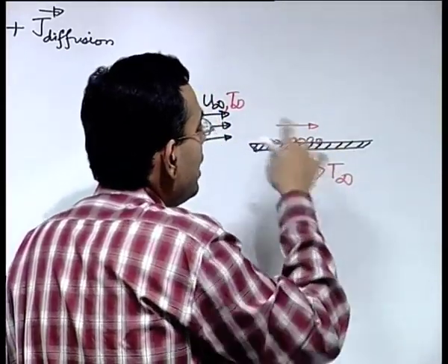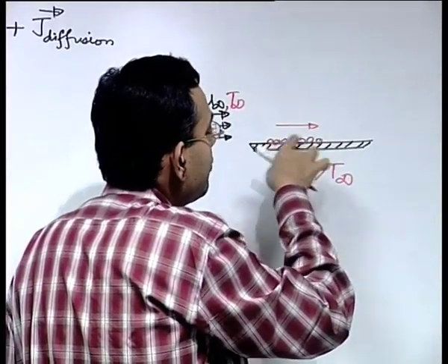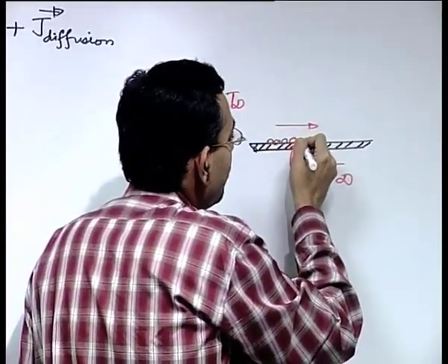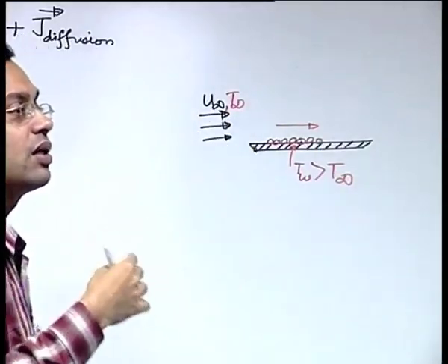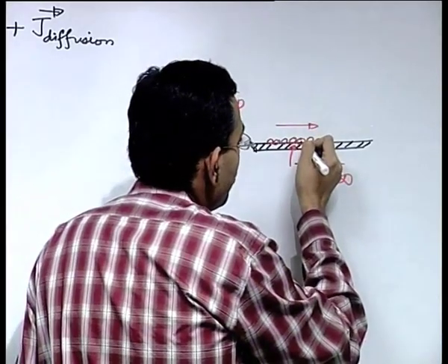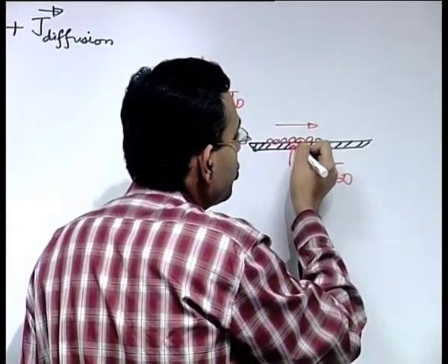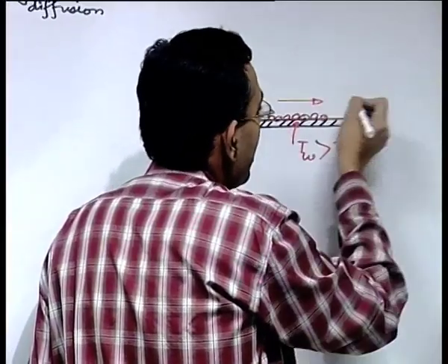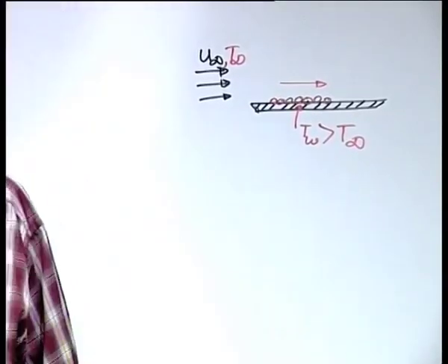So, when the fluid layer is fixed, it cannot be true that by bulk motion this fluid layer is transporting energy. So, how can energy be transported from this layer to the outer layer? That is by the mechanism of conduction. So, in the first layer there is conduction which gives the thermal energy available at the plate to the outer fluid, and then this outer fluid transports it along different directions through a combination of conduction and the bodily movement of the fluid.